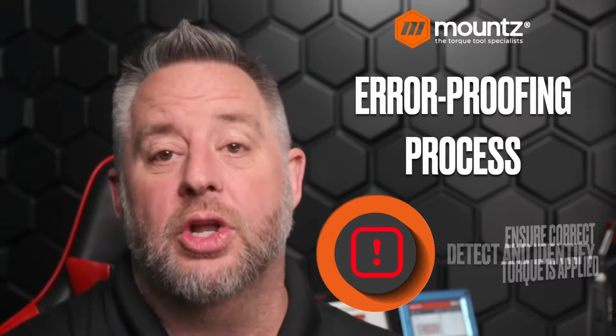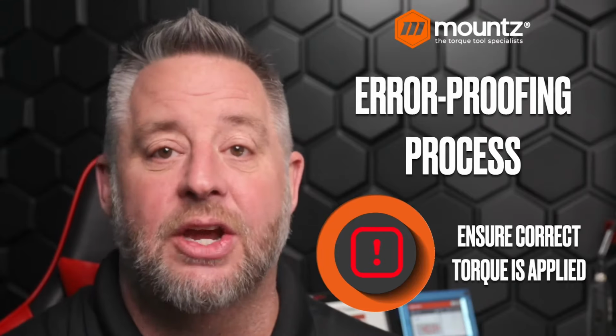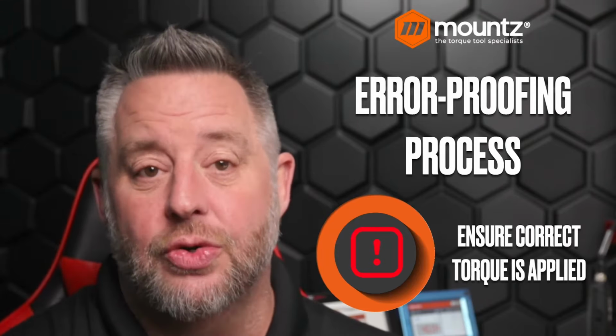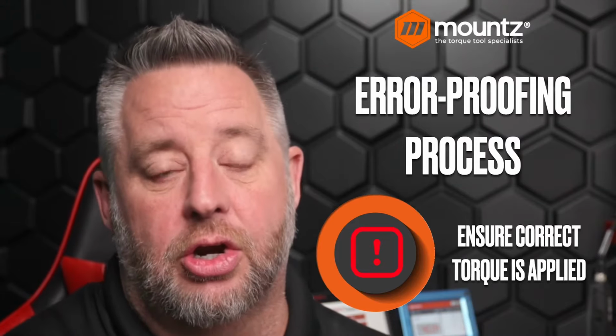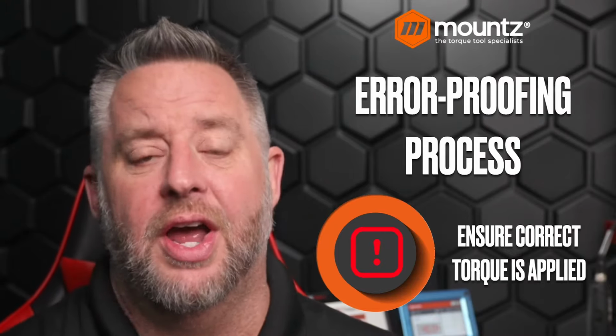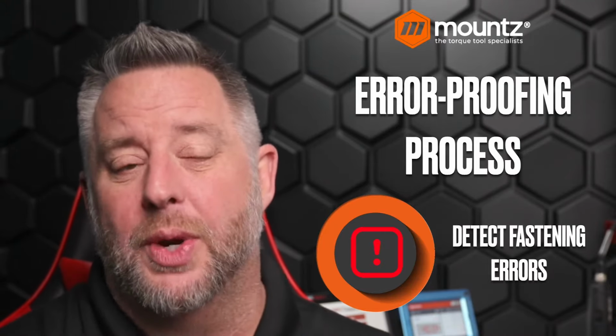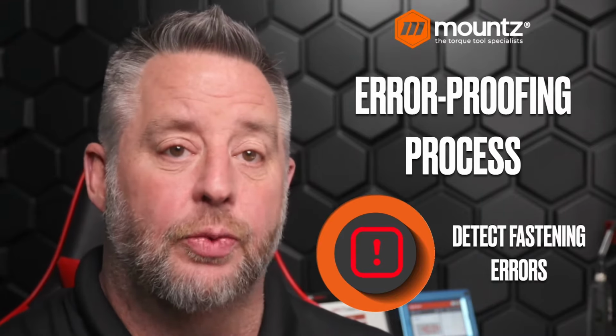And so when we're looking at fastening, we can go ahead and ensure that we're getting the correct torque that we need from our correct part location with our error proofing process, where we can detect if there is a fastening error within that particular rundown.